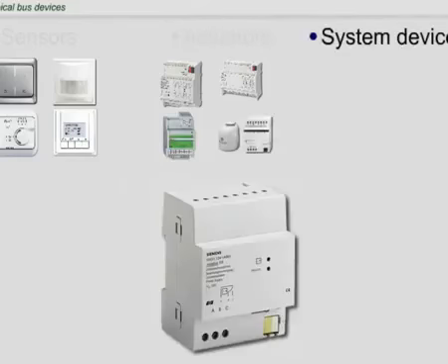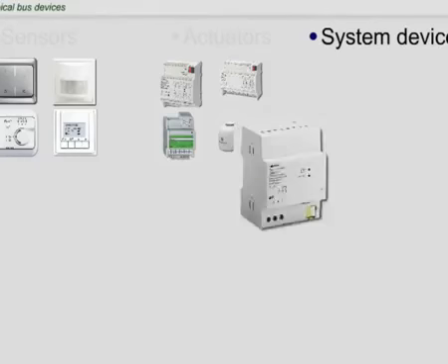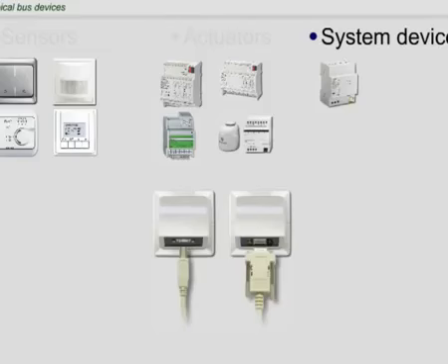The system components of an EIB KNX system also include a power supply with integrated choke, which is available in various performance sizes. It is short-circuit proof and current limited on the bus side. The ETS3 requires a built-in or series PC interface for programming and diagnostics. It is available as an RS-232 or USB interface.